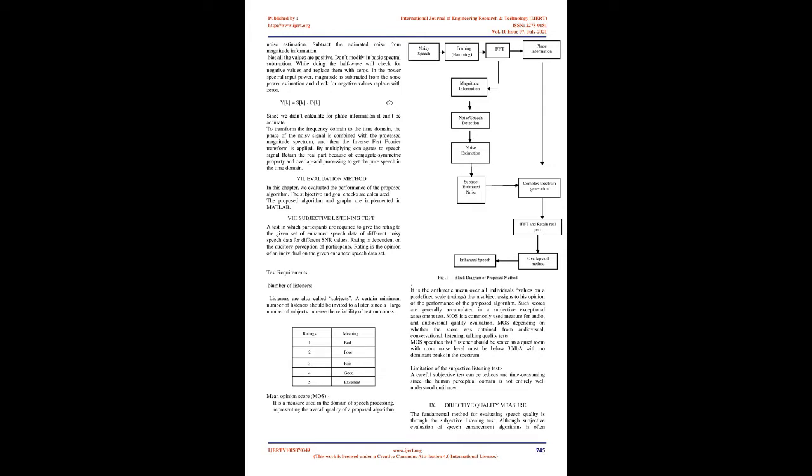4. Overlap add processing. The overlap add approach is used to break long signals into smaller segments for easier processing. FFT convolution makes use of the overlap add approach together with the fast Fourier transform, allowing signals to be convolved by means of multiplying their frequency spectra. The overlap add approach is based on the essential technique: 1. Decompose the signal into easy components. 2. Process each of the components in some beneficial way, and 3. Recombine the processed components into the final signal.